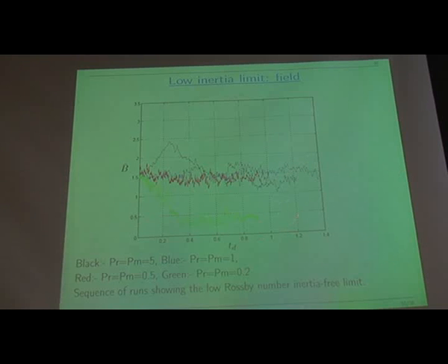So certainly the biggest mistake that everybody made at the beginning was to run their models for too short a time. Virtually everybody did that, because you don't want to sit there all night, do you, watching this thing grind away? So the temptation to cut it short is huge, but it is unfortunately a disastrous thing to do. So you really do have to run these things for a long time. As I said, well, we all made that mistake.